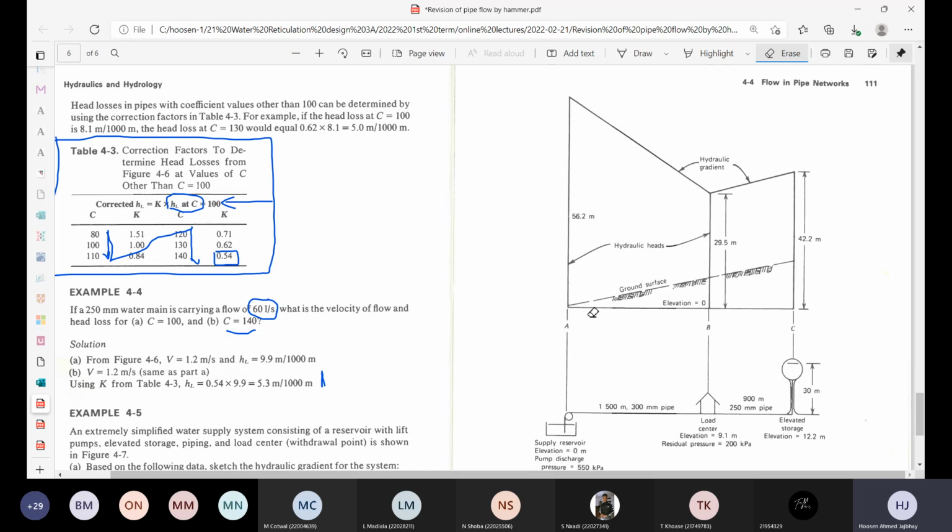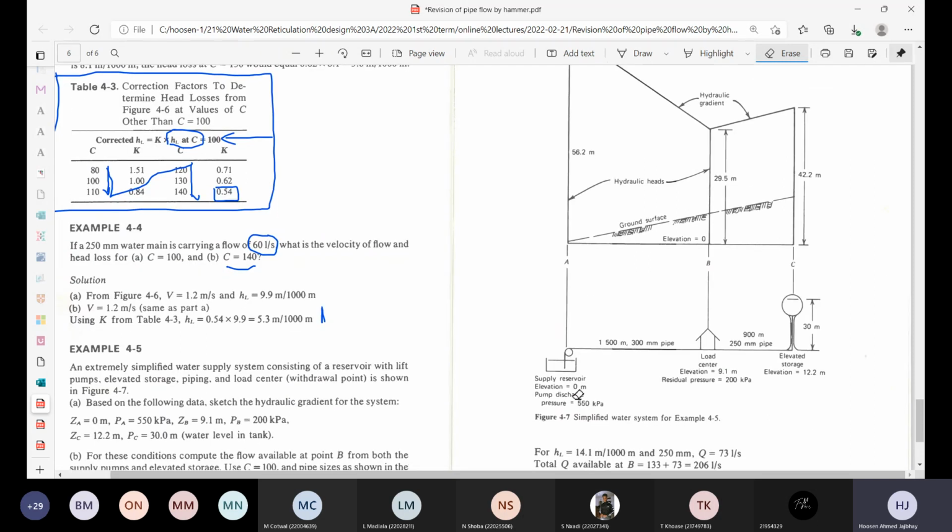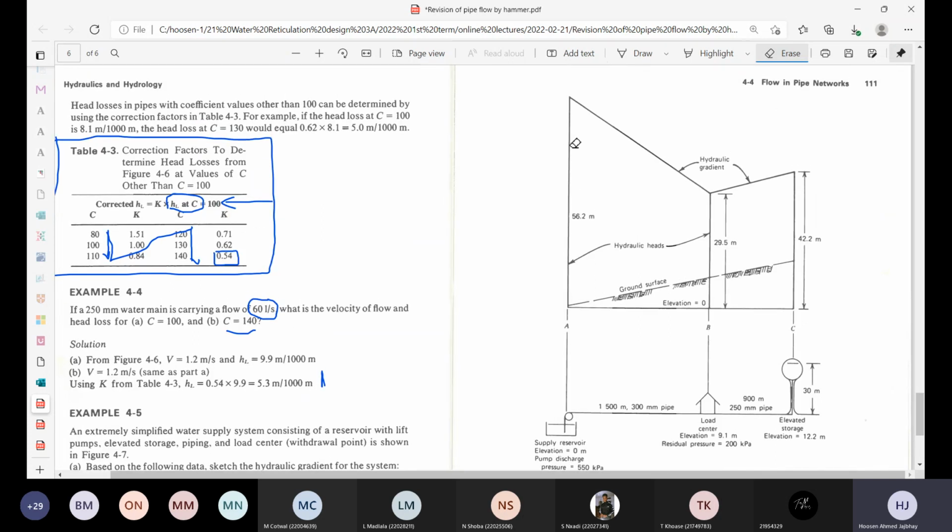And the pressure that that pump creates at point A is 550 kPa. Now, I told you in last week's lecture that we generally would work with meters of head, so we would divide that 550 by 9.79, if I recall, and that would convert that to meters of head at point A. That's the pressure in the pipeline at point A, and that's what has been plotted there.